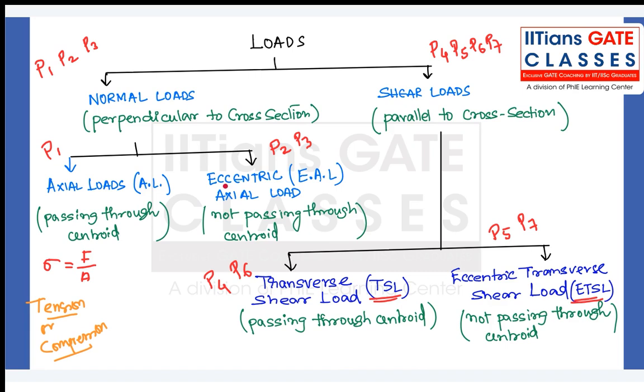How? Let us have an example. Let us try to understand it. Eccentric axial load. If you apply an eccentric axial load, it will produce tension or compression, plus it will also produce bending. It will also produce bending stress. Let me give you an example.